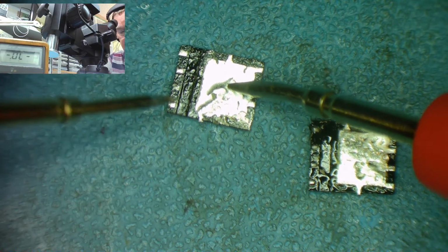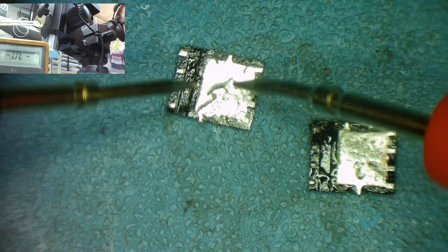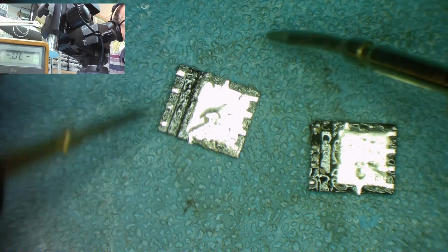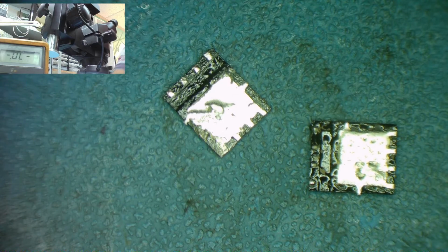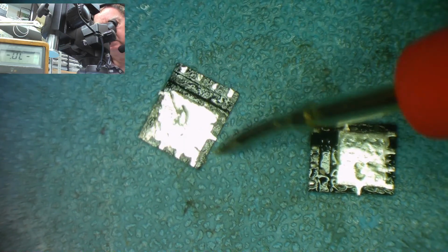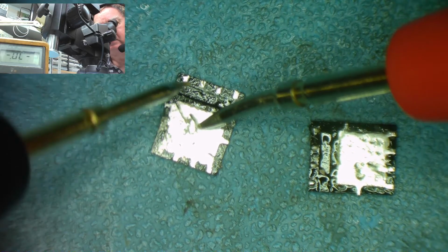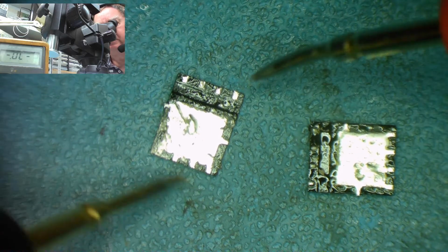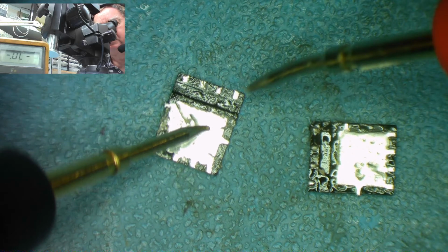Basically, we'll go for one of the middle two. Yeah, it's reading like a diode junction. Let's turn it around a little bit, if I'm looking down the microscope again, because I don't look so stupid when I do it this way. Okay, so that's like a diode junction. This reads like a diode junction both ways, fair enough. Let's see if we can find the gate. No, that's a diode junction, so try this end.